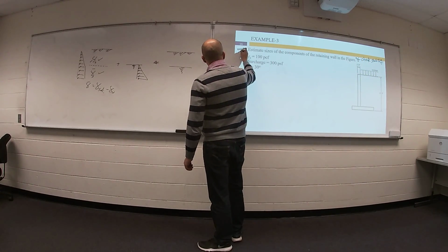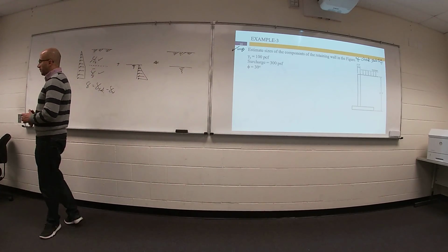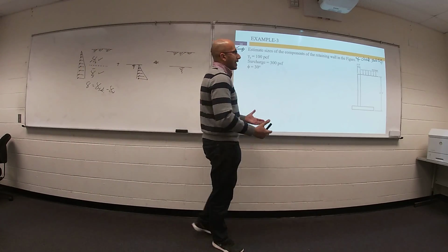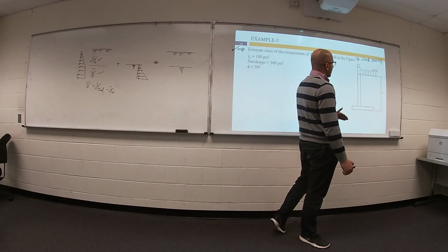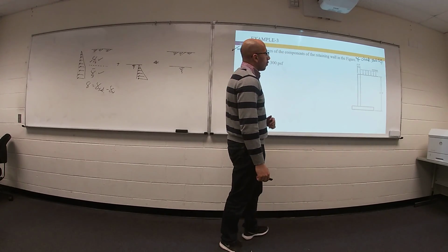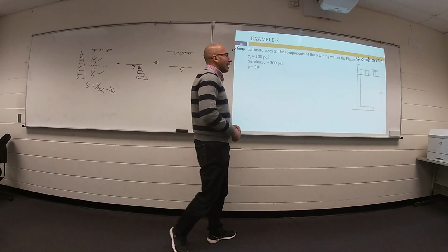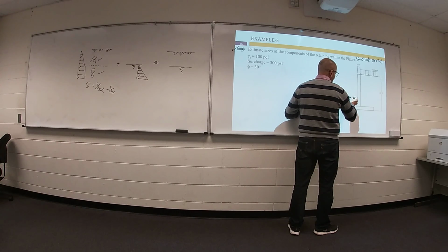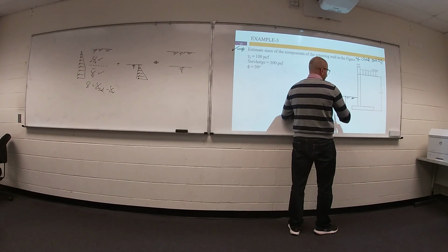Your problem in the exam will look like this. I will give you a retaining wall without dimensions, so please go ahead and assume your dimensions. Once you did your dimensions, go ahead and make a check of stability against overturning and against sliding. Something is missed here. We have soil on the other side with depth equal 6 feet.